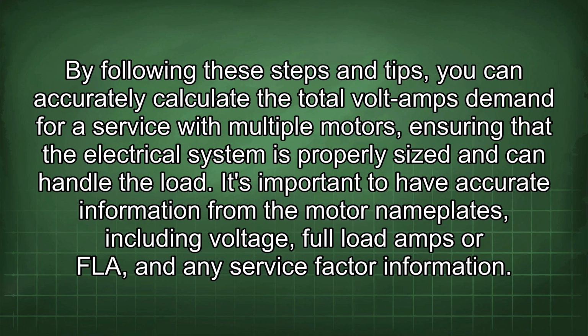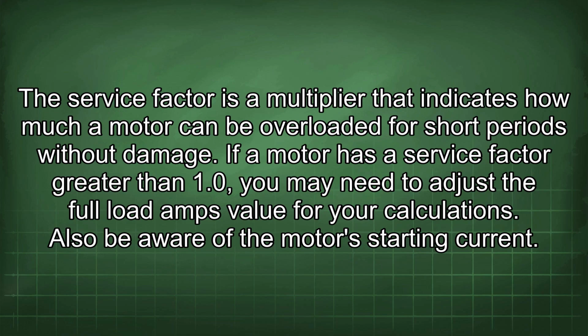It's important to have accurate information from the motor nameplates, including voltage, full load amps or FLA, and any service factor information. The service factor is a multiplier that indicates how much a motor can be overloaded for short periods without damage. If a motor has a service factor greater than 1.0, you may need to adjust the full load amps value for your calculations.